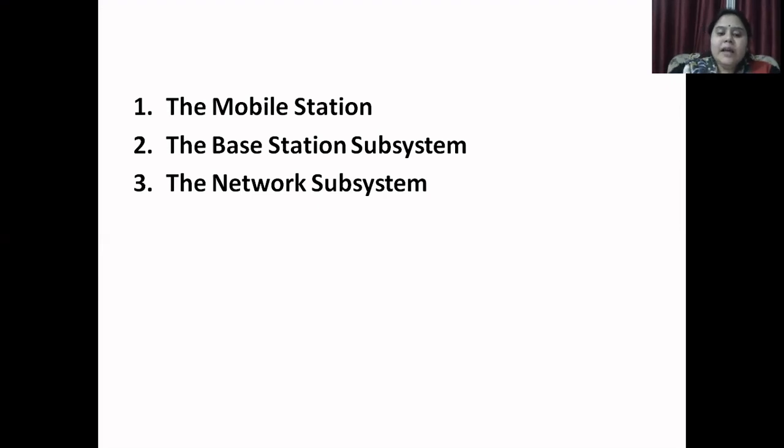It works like any ISDN and PSTN switching center and performs the switching of calls between the mobile users and between the mobile and fixed network users. In addition to the normal call switching functions, it also handles mobility management. The information on the registration, authentication, location, call handovers, and routing in case of roaming are all handled by the MSC.